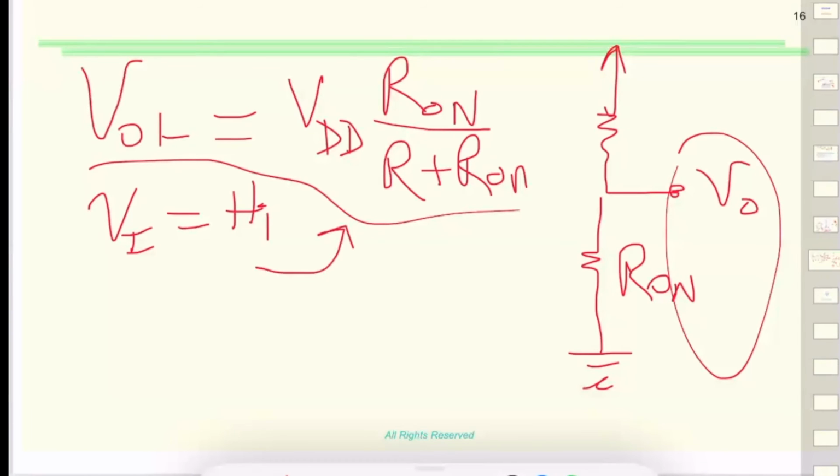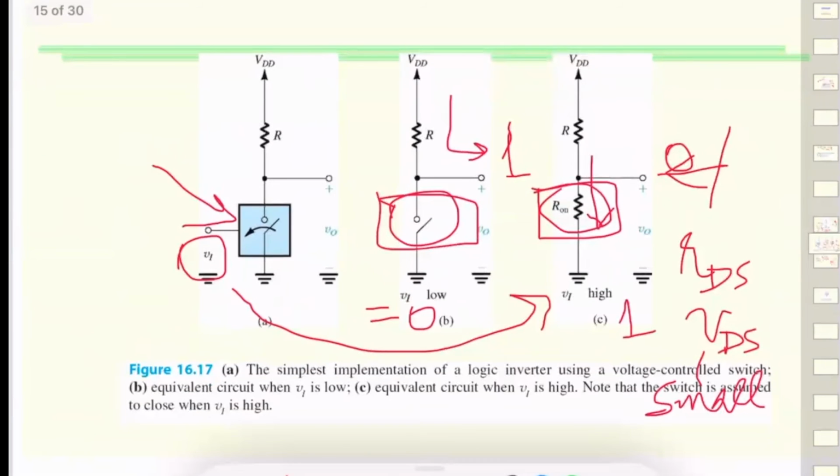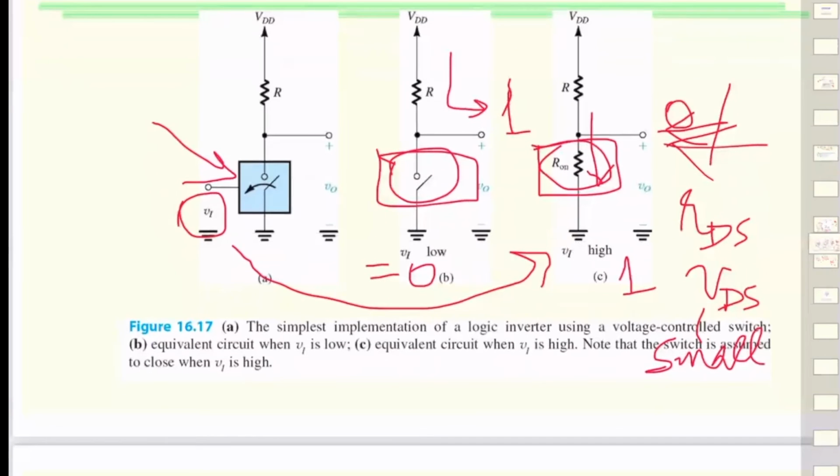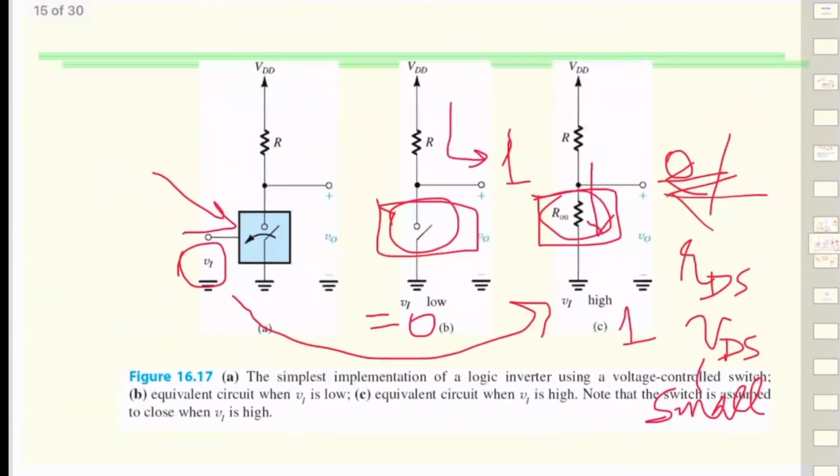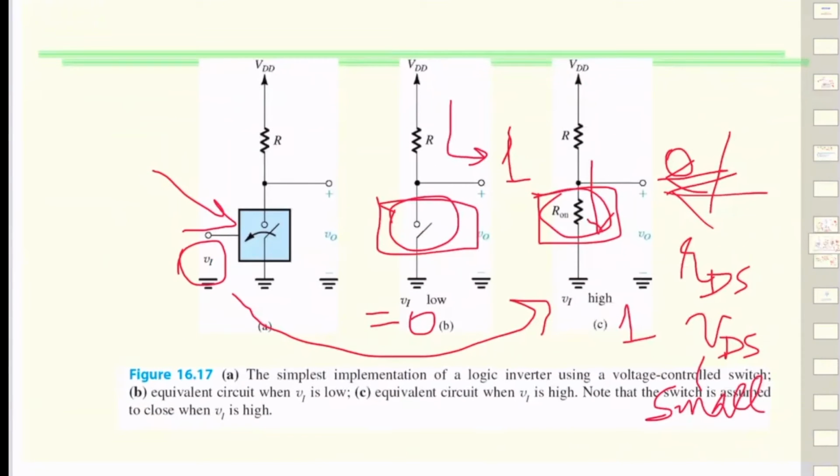So even though we say there's no signal, there is some signal because, if you look at it from this side, it's a voltage divider. So we do have a small resistance there and hence a small voltage. But that's from the voltage transfer characteristic. So this still gives us a low output. All right, so that's the actual implementation of an inverter, in this case a switch.